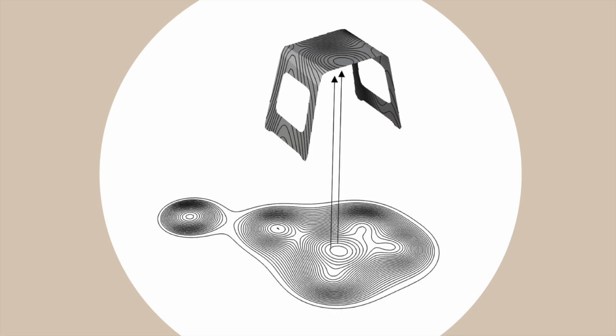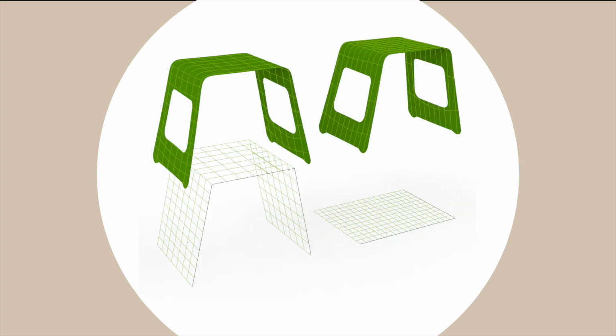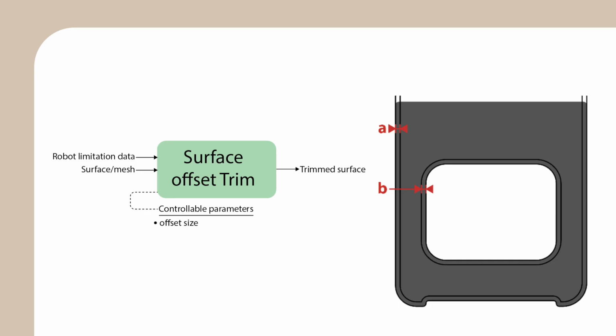The Metaballs pattern generator is an example of a field-based pattern generator and creates curves surrounding input points on a 2-dimensional plane. The curves can be projected onto a curved surface. However, warping occurs with these 2-dimensional projections onto 3-dimensional surfaces, unlike the growth-based curves which account for the curved product's form. Another computational design tool type which was discovered to be valuable for use in the design process are trimming tools for the surfaces.